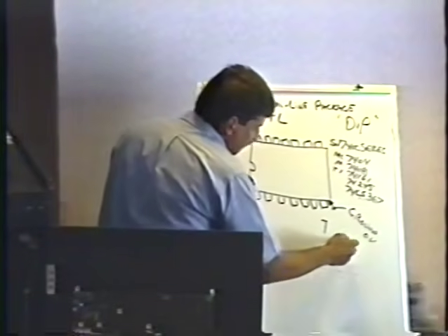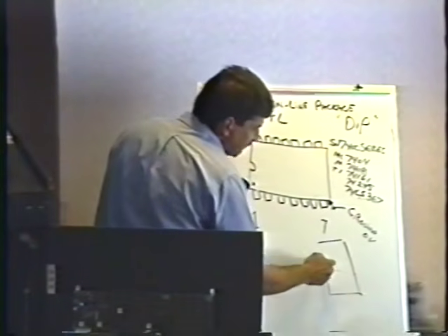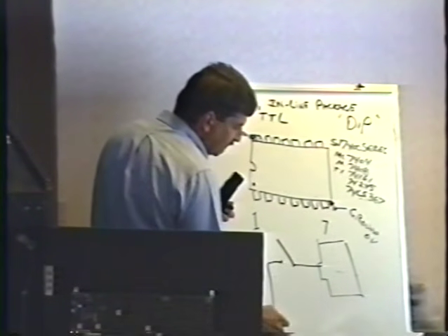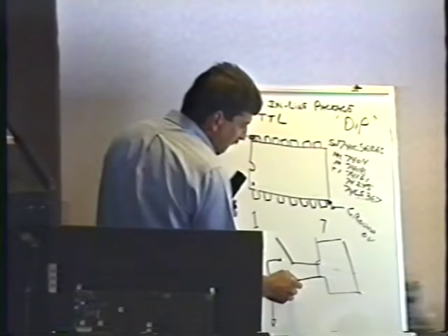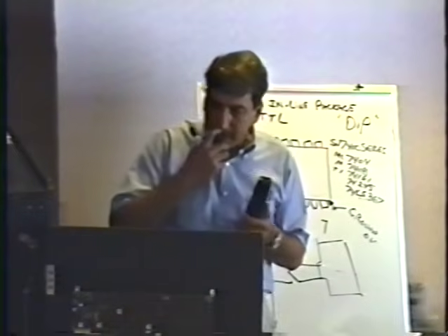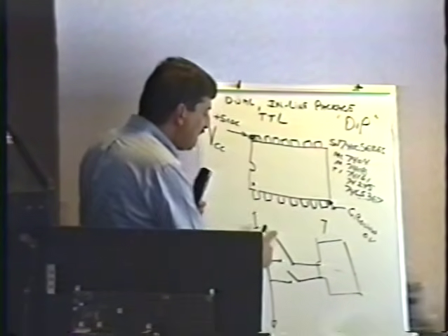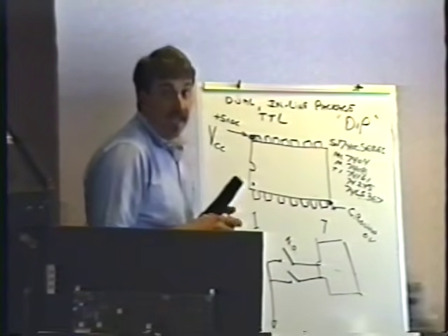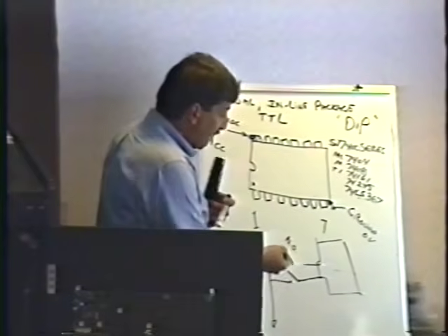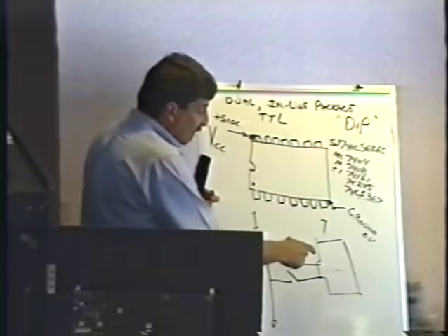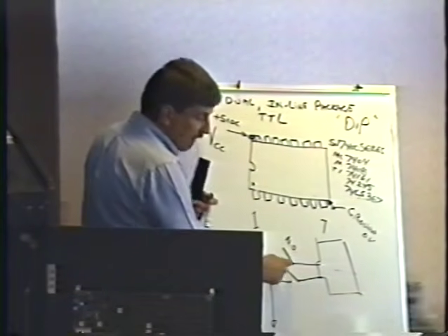In a video game, you have the logic board, as you see in the drawing on that page. And the logic board is connected to the switches which are in the control panel of the game. You know, all the switches that are in the control panel. And those switches are what we call normally open switches, abbreviated NO, normally open. Meaning that when you're not pressing the button, the switch is not connected, right? It's open. What that means is that we've got quite a long wire from the logic board up to the control panel.